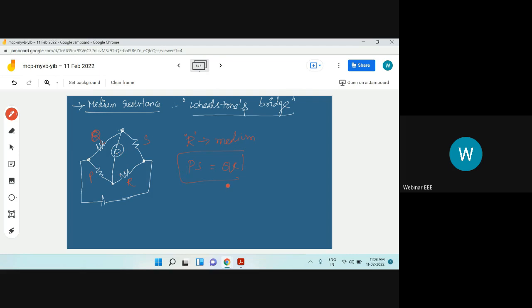While coming to the accuracy, Wheatstone's bridge is a more accurate bridge. And here you should know a term called sensitivity. Sensitivity is nothing but deflection per current passed through the galvanometer. If it is voltage sensitivity, then SV is equal to deflection of the galvanometer per voltage seen across the galvanometer terminals. And one more term you can see is bridge sensitivity. Bridge sensitivity is nothing but a ratio of internal resistances. These are the basic parameters that you have to know regarding the calculation of bridges. In bridge circuits, sensitivity is a very important factor which is used to identify the accuracy, precision, etc. So we have to remember these points under Wheatstone's bridge.